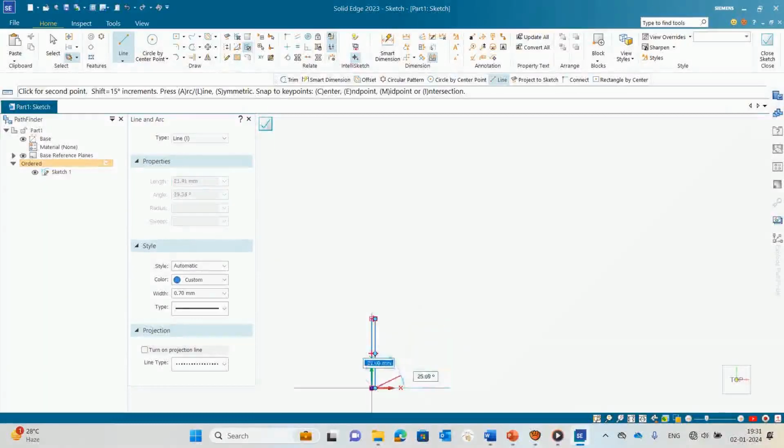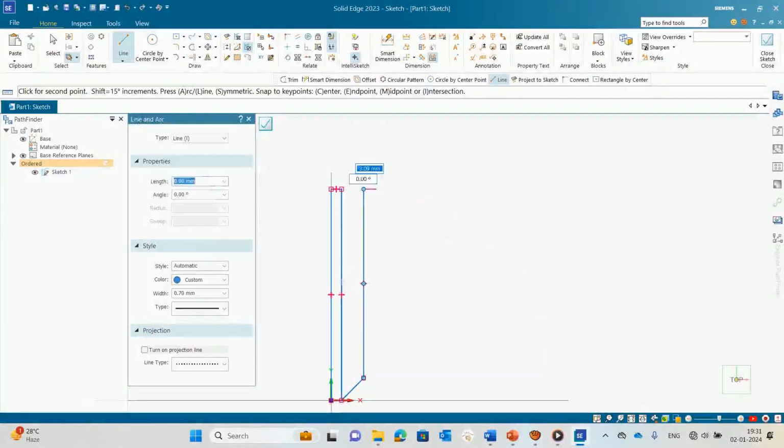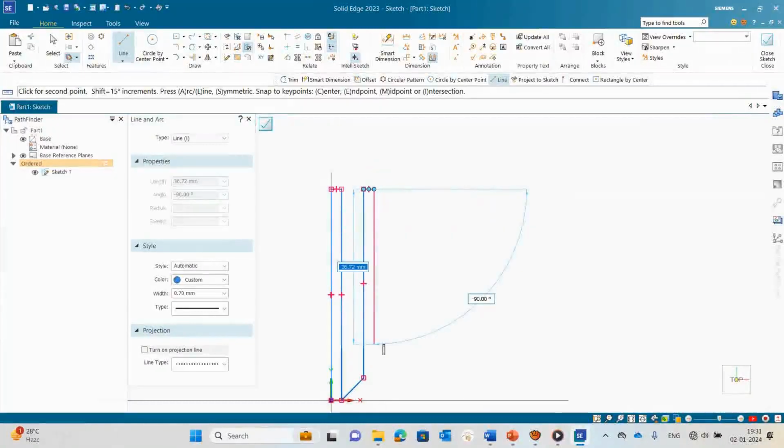Then finish. Then I will create around 7.5 mm at a 45 degree angle, and increase this to the corresponding endpoint. Then I will increase this to 2.50, meaning air is entering through the 0.5 orifice gap. Here I will keep the gap between the liquid tube and orifice exit about 1.25.